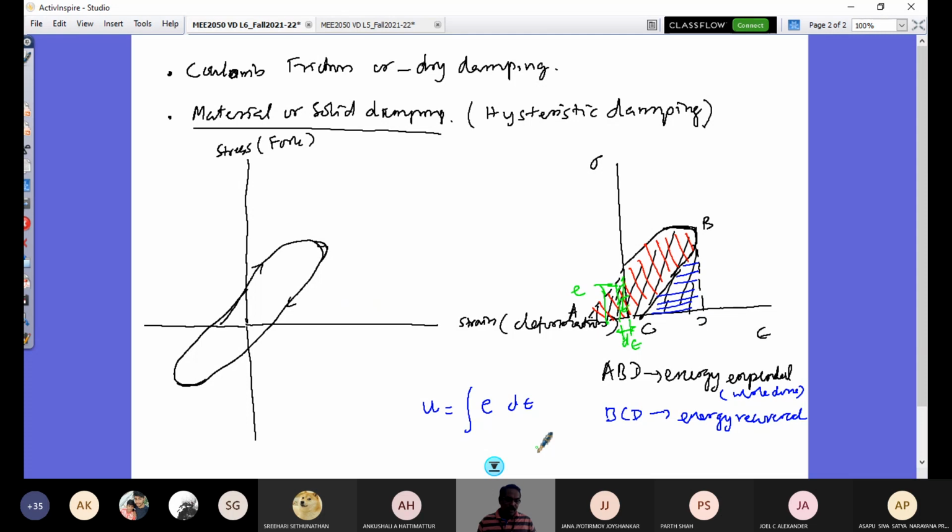So this hysteresis loop for elastic material, if you look at, it would be like this, right? If you go in for hyperelastic material, then there is something called more involved viscoelastic nature and so on. That becomes more material modeling, where you have to understand the constitutive model and so on. But we are not going to discuss that at the moment. We're going to just look at the elastic material, and then there is rubbing of intermolecular planes, then the energy can be dissipated, and that is what is kind of solid damping.